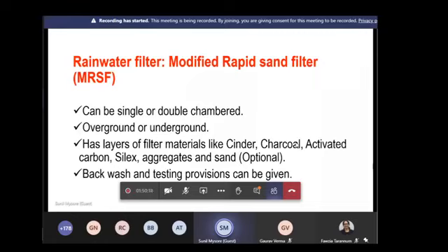There's no rule that this has to be the volume. Depending on your judgment, depending on the kind of contamination you see, you can change the size of the settling tank. For normal urban India, 1 liter per square meter is good enough. But depending on the sensitivity, for example, if the water is stored for hospital purposes, or used for some treatment or jeans washing, where the quality is important, you have to go for a slightly higher settling tank. Then the filtration, a large amount of cinder and activated carbon, will take care of this dust. Can I move on?